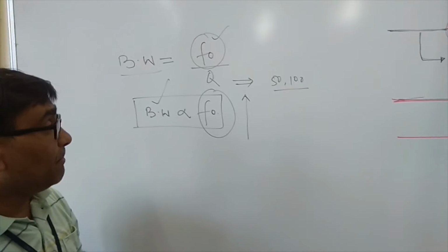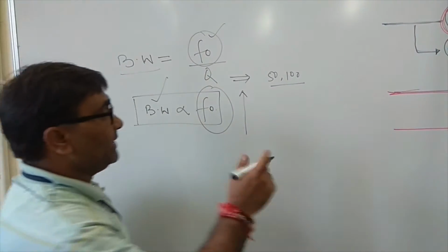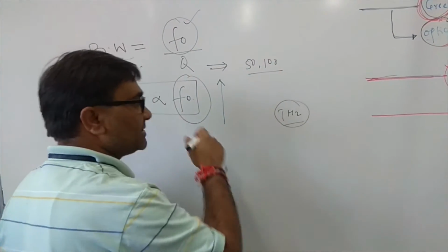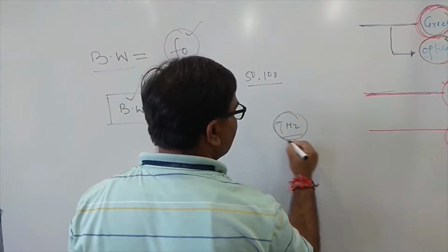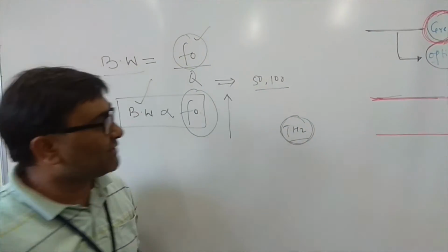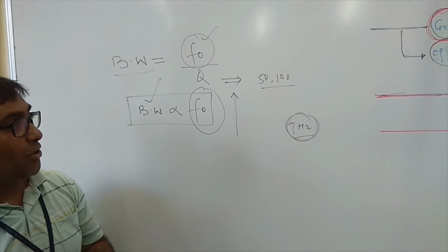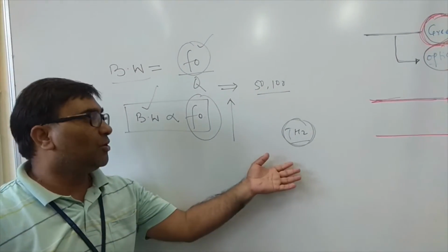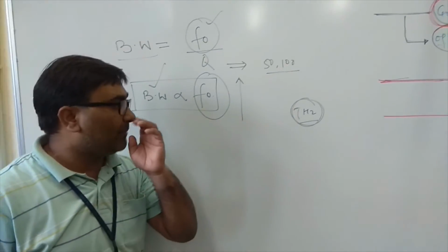In microwave, the frequency is also very high, but not up to optical fiber, because when we go from gigahertz to terahertz, microwave has some disadvantage. What is this disadvantage? Since microwave components are lumped components, if you use very high frequency, distributed phenomena will cause some problems.